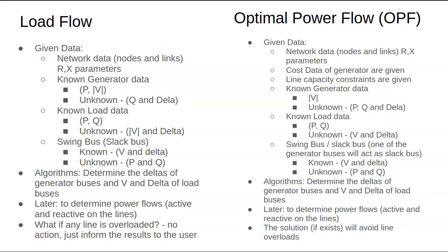So now you go back to load flow, apply that 400 and do the load flow. Then that particular line will overload. Then, if this line is getting overloaded, I will add one more line there or something like that. Then you are allowed to generate more. So in order to increase the utilization of this generator, you may have to construct a line somewhere else. So all these things.